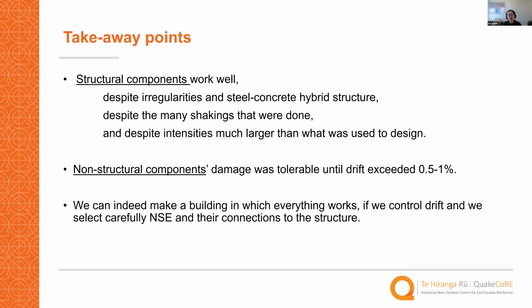For the structural components, although the building is quite irregular and is a hybrid steel concrete building, which is relatively complex, and although we ran many rounds of shaking, and the intensity of the shaking was quite high, heavy compared to what we used for our design, the structural components performed really well. There was only very minor damage, and it was at a very late stage.